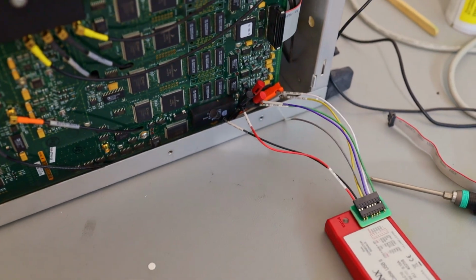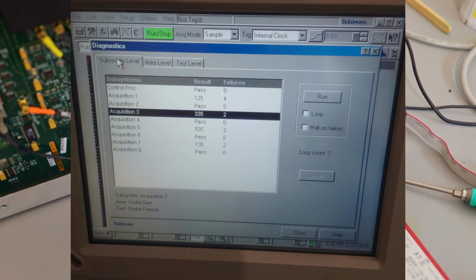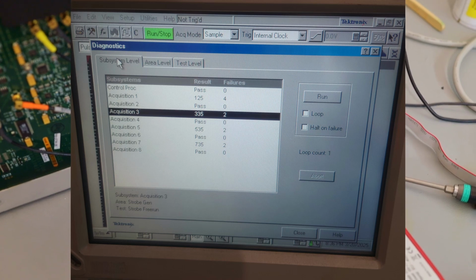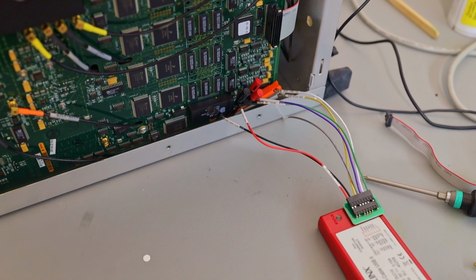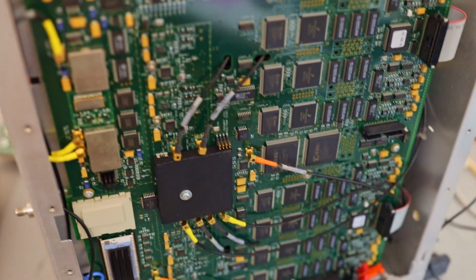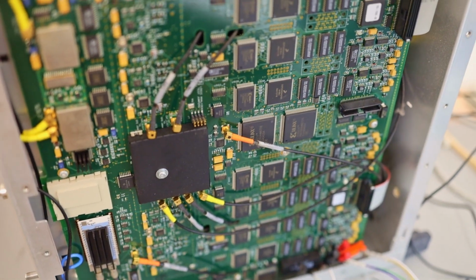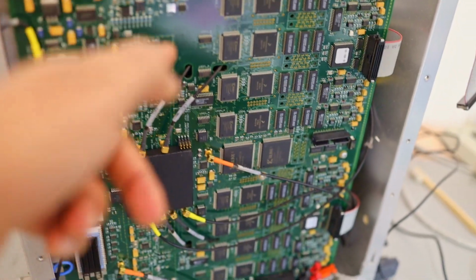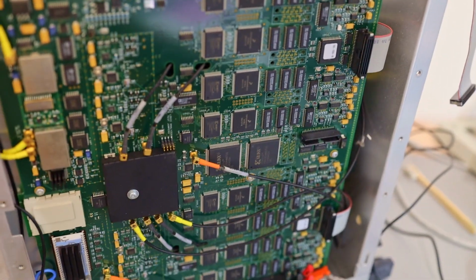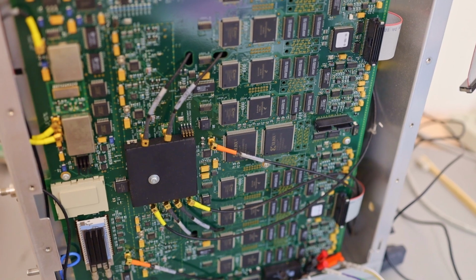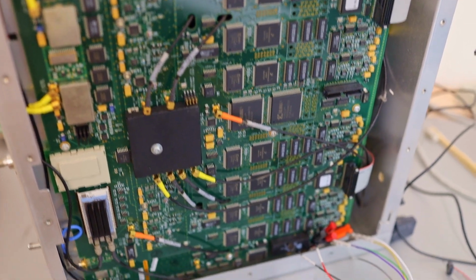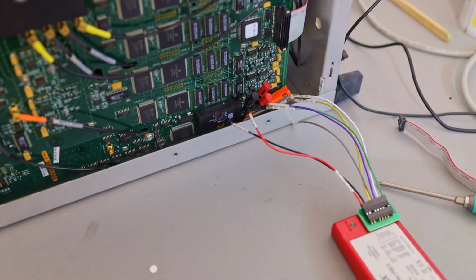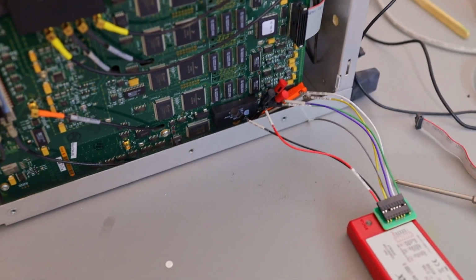So it appears that, due to these compensation errors and normal channel acquisition errors on the strobe, I want to verify if the content of the PLDs is correct. Some guy from Austria on the EEVblog platform suggested that these PLDs, due to the heat and long operation, can get bit flips or memory corruption and need an update. He has also published the JED files, or bitstream files, for them.